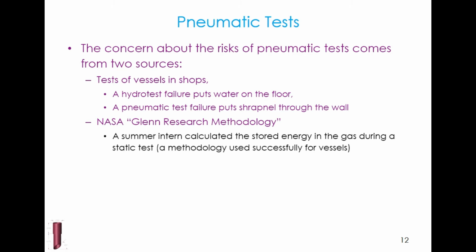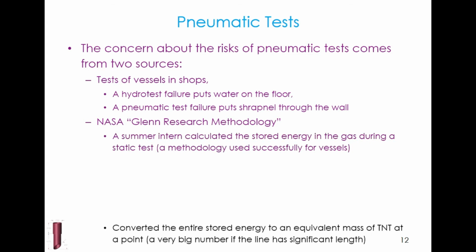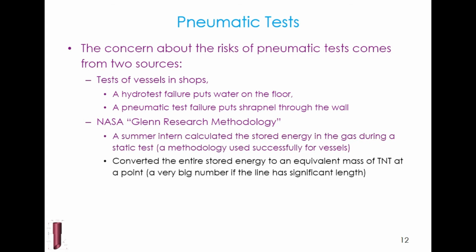A summer intern calculated the stored energy in a gas during a static test. This is a methodology that was used successfully for vessels since the 1920s. He then converted the entire stored energy to an equivalent mass of TNT at a point. That's a big number if the line has any significant length.